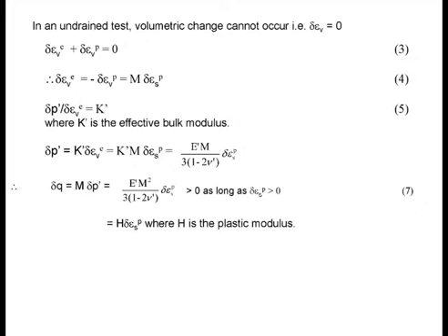And in a sense, you can write this whole group of terms as H, where you can say H is some form of plastic modulus. That is the slope, the gradient of the stress strain curve after yielding. After yielding. Not before yielding. Before yielding is obviously related to Hooke's law. But after yielding, some of you might have plotted the stress strain curve, and you find that in this kind of situation, the stress strain curve just keeps going up. It never levels off.